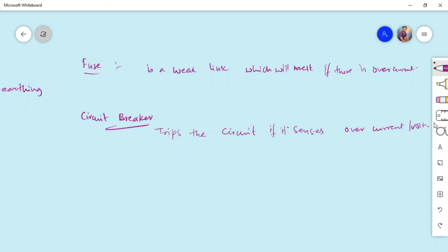There are advantages and disadvantages, and I want you to go through those, but these are all safety devices for any sort of electrical equipment, for our protection and device protection especially. A circuit breaker has its own ampere rating, like 6 amps, 10 amps and 20 amps. If it attains that rating, it will automatically trip off, and if it is a short circuit, with high amperage, it will trip off immediately. So these are the safety devices that we use.